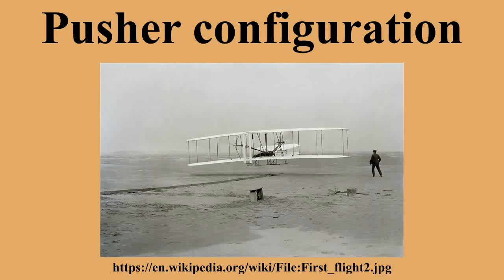Propeller and safety. In case of propeller tail proximity, a blade break can hit the tail or produce destructive vibrations leading to a loss of control. Crew members risk striking the propeller while attempting to bail out of a single-engined airplane with a pusher prop. At least one early ejector seat was designed specifically to counter this risk. Some modern light aircraft include a parachute system that saves the entire aircraft, thus averting the need to bail out.